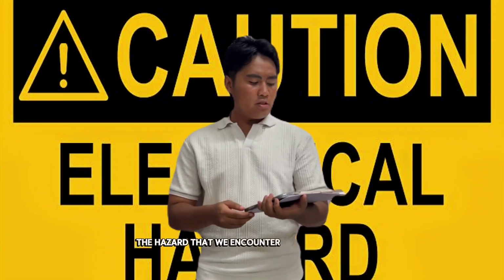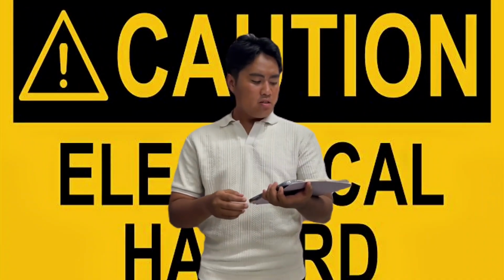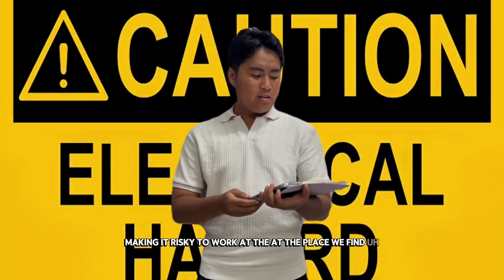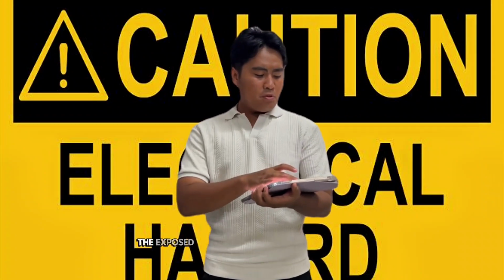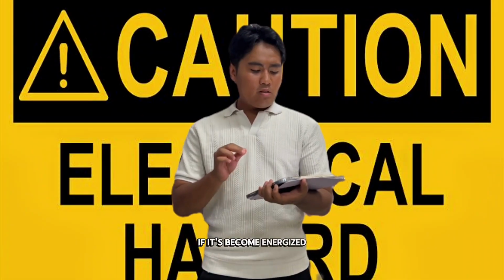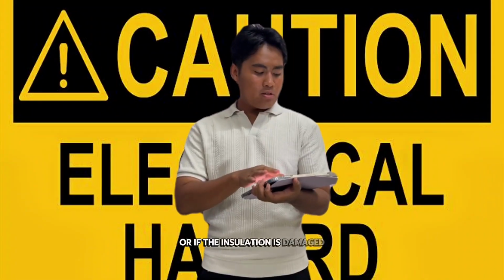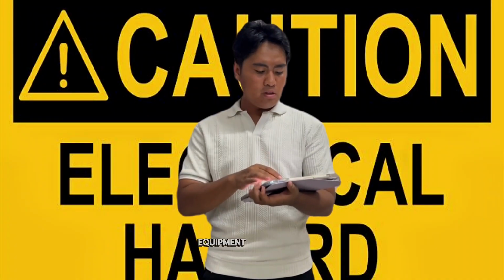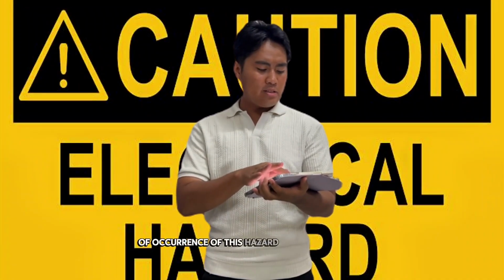The hazard that we encounter is a cable hanging without proper protection, support or termination, making it risky to work at the place. We found this hazard at the mechatronic system design lab. The exposed cable poses a risk of electric shock if it becomes energized or if the installation is damaged. It may lead to short circuits, electrical faults, or fire hazards, which could cause injury and damage to equipment or property. The likelihood of occurrence of this hazard is considered high.